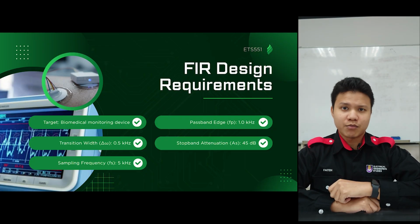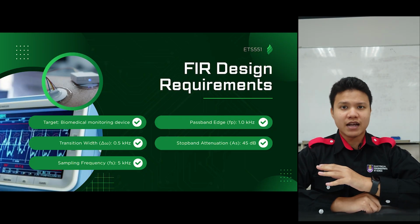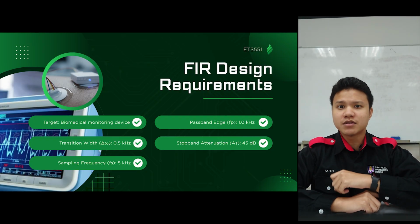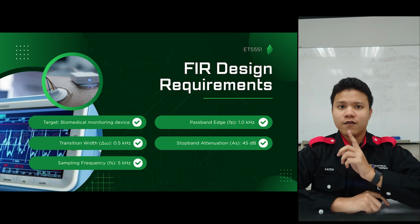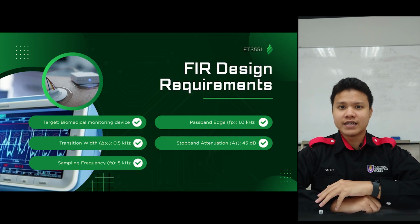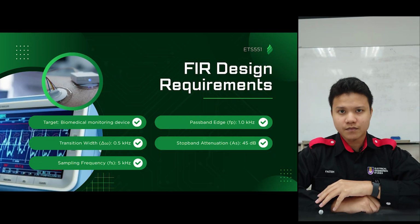Our given system parameters require a passband up to 1 kHz, a transition width of 0.5 kHz, a minimum stopband attenuation of 45 decibels, and an operating sampling rate of 5 kHz.